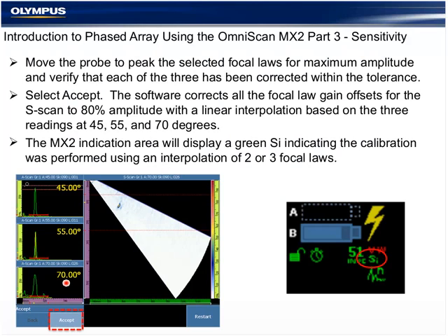So when we can't complete the wizard for the 75-degree shear wave, but we want to include it because it's very useful for identifying and finding defects, we would enter a 75-degree sector scan, but only select the 70 as one of our 3 angles. This way, the software will fill in the rest of the predicted amplitude and not turn it solid red, which would impede our inspection.